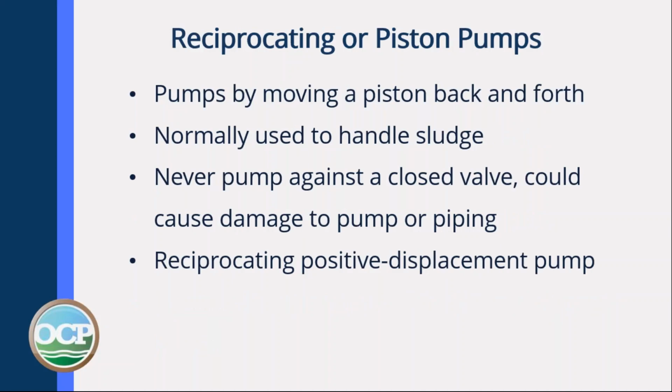Reciprocating or piston pumps. These pump by moving a piston back and forth. These are normally what your sludge pumps are. With this pump, you never want to pump against a closed valve, because if you do, it will cause damage to the pump or the piping. It's a reciprocating positive displacement pump.